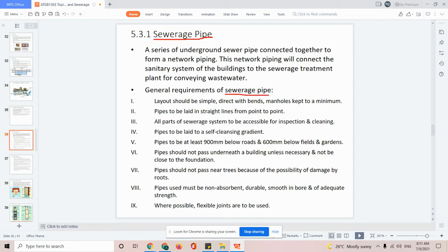As usual, when it comes to the piping system, you have a few requirements on how we want to lay the pipe. There are actually two methods of installing the pipe. What we can do is cut it open. We call it the open cut method. We can have an excavator with a scoop, and then we can just open it up. We can just excavate it, meaning we cut a hole.